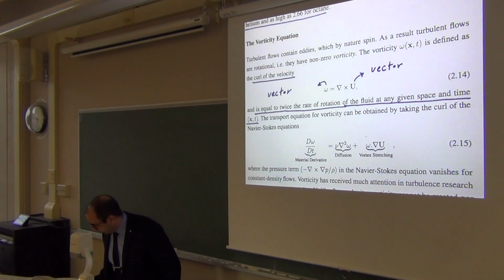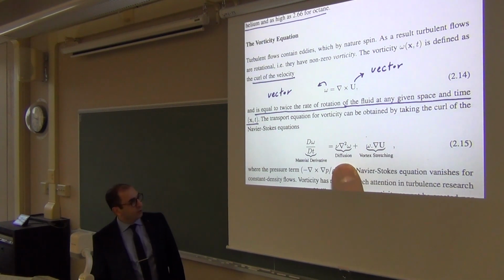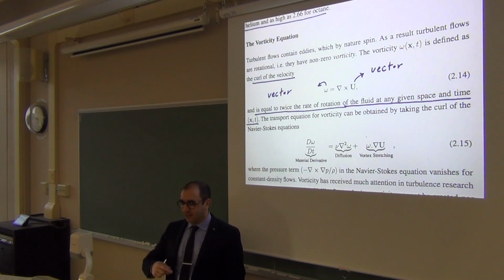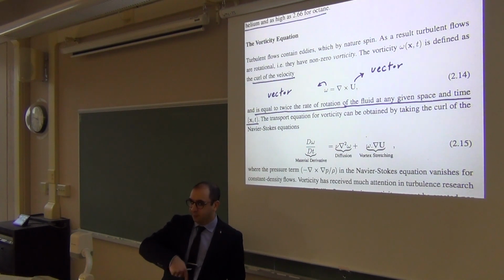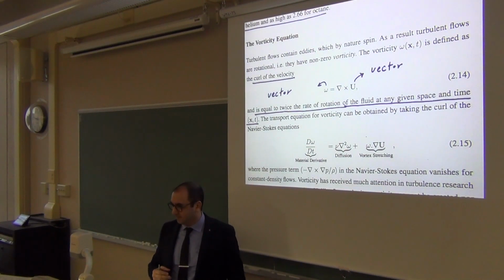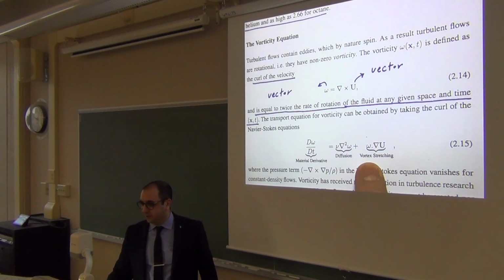this following equation. So surprisingly, the Laplacian showed up again as a diffusion process with kinematic viscosity nu, which means that vorticity kind of diffuses. It's kind of fun to think about. If you spin a piece of fluid, it doesn't stay there. It sort of diffuses into the background. It's really fun. But it also stretches.